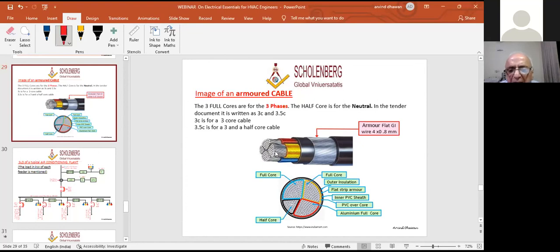So there will be air gaps inside. If current flows through the air gap, then the current starts jumping from one strand to the other strand, resulting in heating. When heating starts, we get carbonization. When carbonization starts, heating increases and the insulation burns out. When the insulation burns out, we get a short circuit and fires. So on these strands, this is that strand.